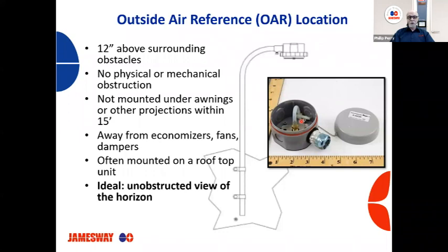Another thing is moisture in the wintertime can collect in these, especially when the tubing goes up through your plenum area and on up into the roof. That warm air, as it goes into the outside air, can collect moisture, and sometimes you just have to blow the air out of it, or blow the moisture out of them a couple times just to keep them free so that they're measuring properly.